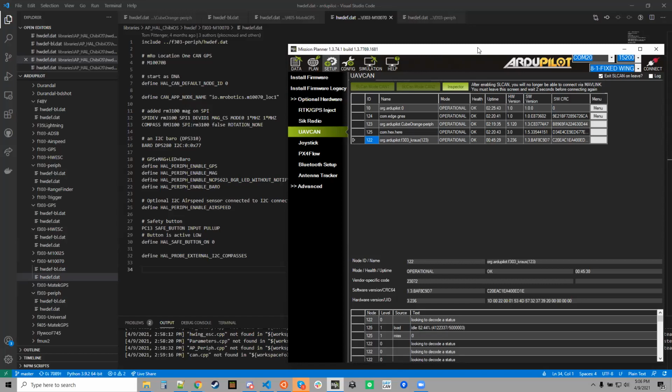If you want to be able to connect multiple of the device on the bus, you have to do it that way. So for example, if you're selling CAN bus GPS modules and you want your users to be able to trivially just plug in 2 of them, and they automatically get assigned different IDs, then you'd want to default that to 0. But some of our vendors have deliberately chosen non-zero, which means it comes up with a fixed ID, which makes it easier for some users and harder for others.